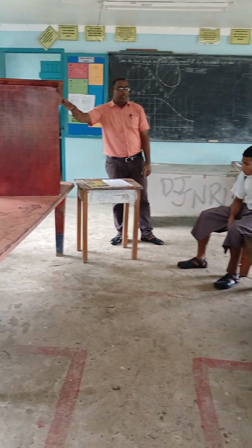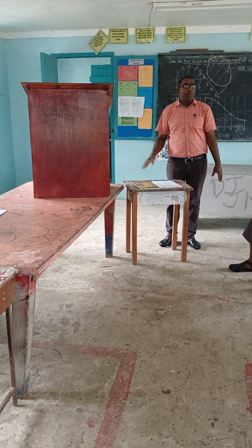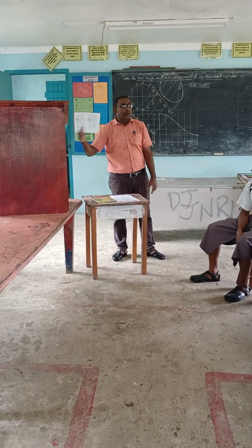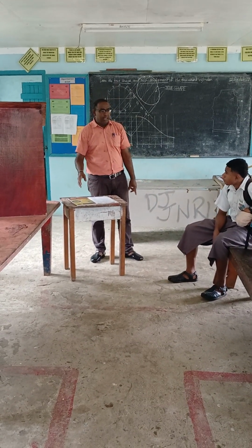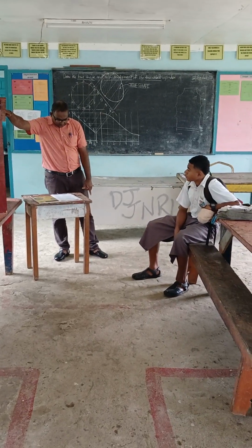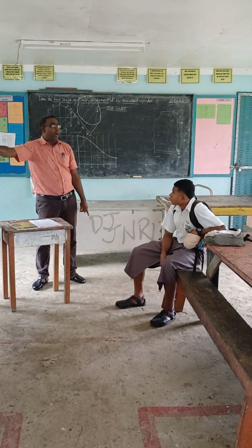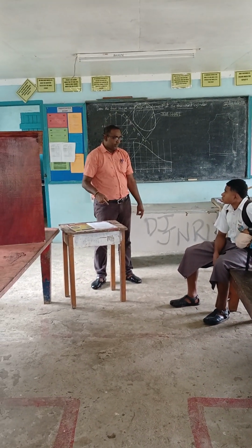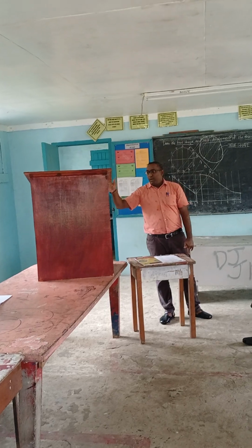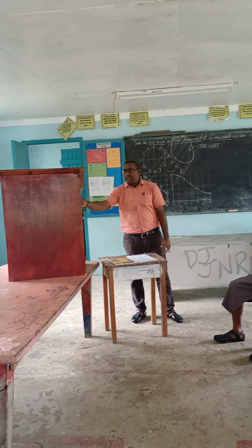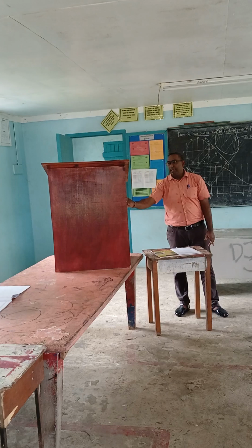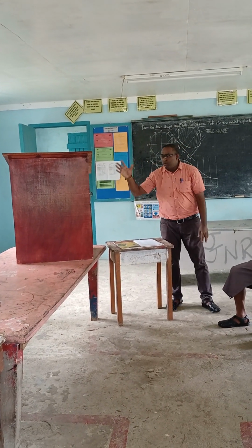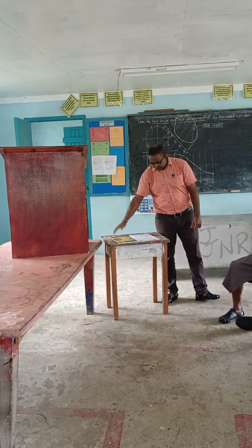Once the pieces were joined together, we tried to fix or put fillers around so that no gaps were seen. And then we used a claw hammer for hammering the top using the panel pin. Once this technical drawing table was ready, we used the garnet paper to make it smooth, and then we applied the finishes.